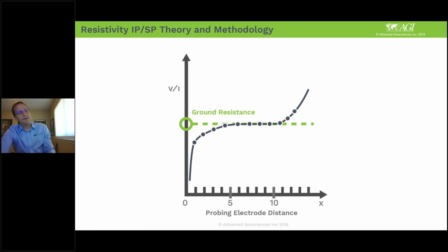So let's say your rover electrode is approaching that current, but near that current is also a fence that goes around the site and loops back to where the other current electrode is at the grounding grid, like a perimeter fence.